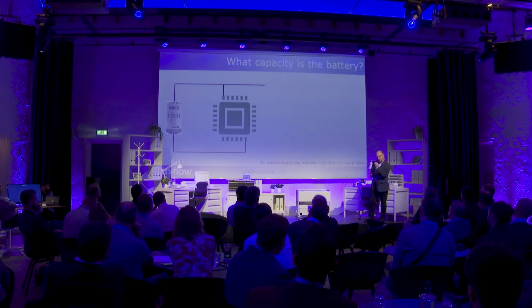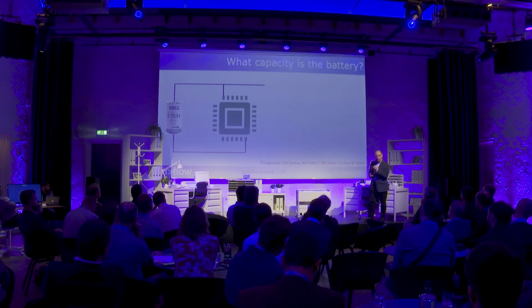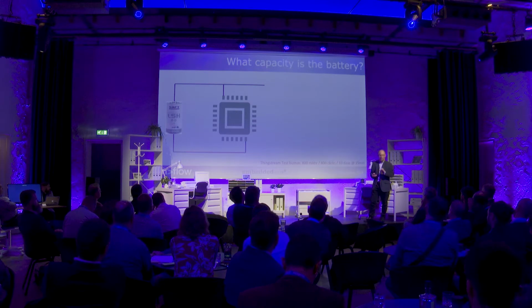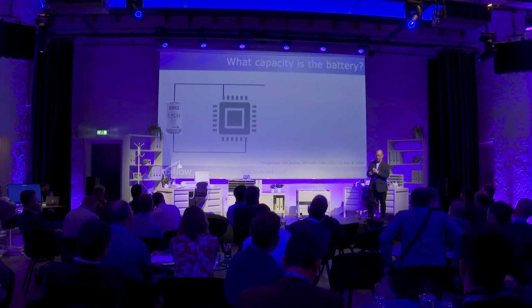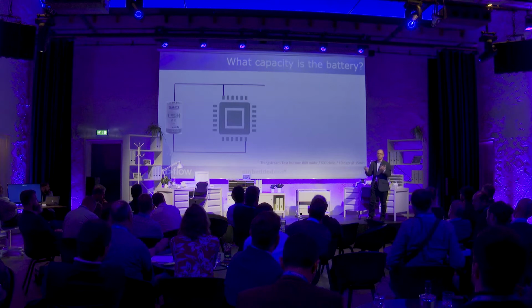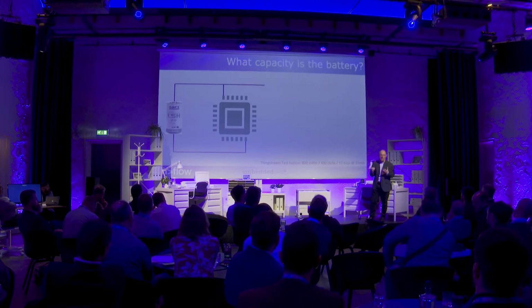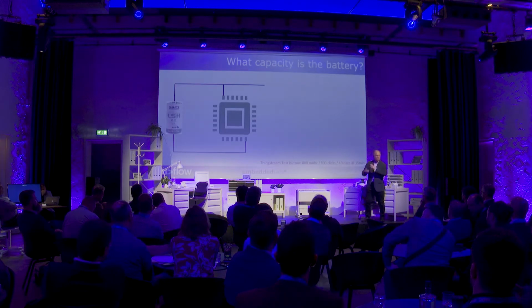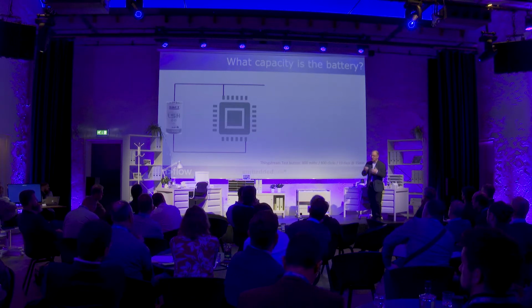So it's that microcontroller which is really the power use case. That's likely to be on all of the time, and whether it takes an amp, unlikely, or 100 nanoamps is going to make a big difference about the power and the battery sizing. So the question comes down to, what size battery do I need? And of course, we know this, but what we're actually saying is, how many service calls do you need to put in to send someone out to fix the system because of a battery?